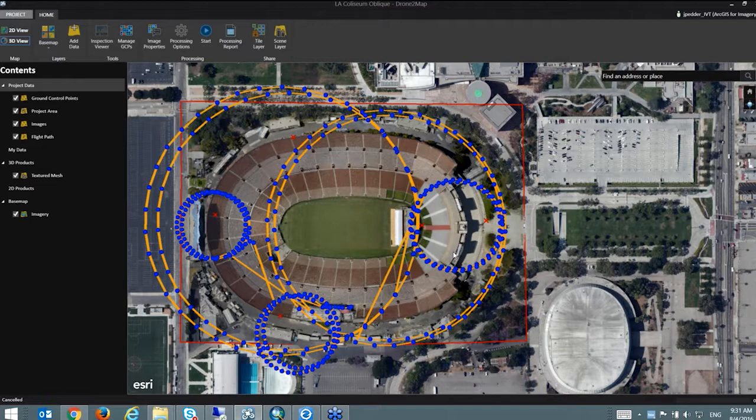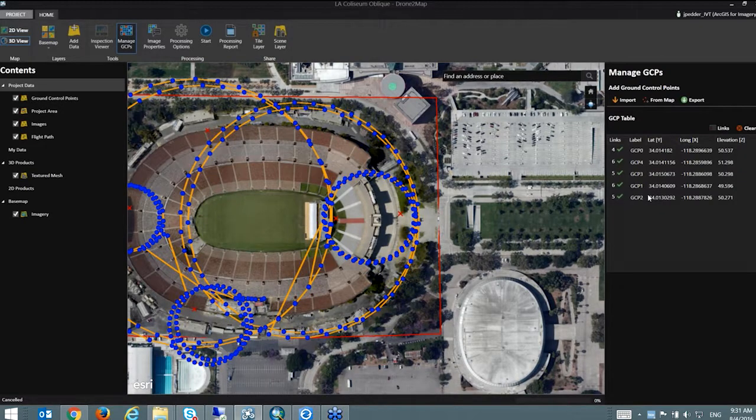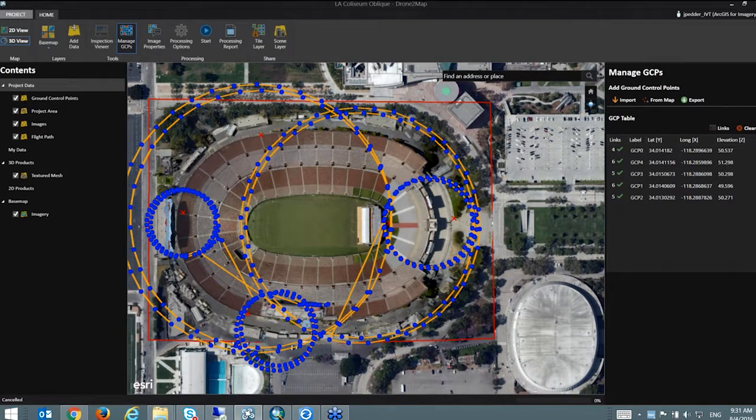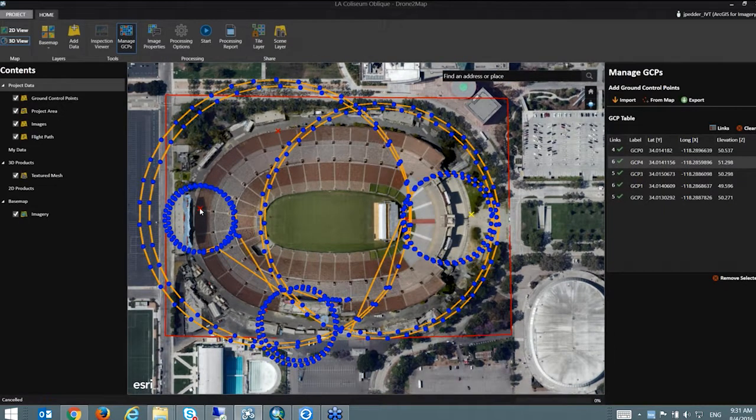really captured that. But also, because the stadium is above ground, it was best for us to actually take some ground control points and to optimize the imagery. So if I click on the ground control points, you can see that we brought ground control points in. So we had our collector team on site, and they were using the new capabilities of the collector app, which is the high definition GPS. So they were capturing sub-foot measurements. I think there was down to about 8-inch measurements on ground control points. The ground control points here are shown as the red X's on the screen.